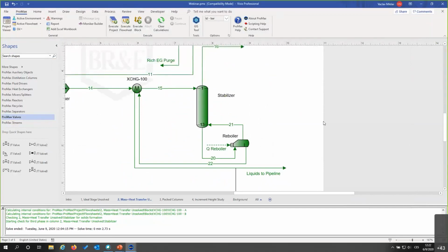What you can always do is reach out to a vendor, and he will probably give you a trustworthy value for HETP, maybe even over some range of F factor or something like that. But what if you want to investigate different feeds? What if you want to investigate multiple packing types? What if you want to change the operating conditions significantly? What if you want to operate at different pressures and temperatures? That's of course going to affect the physical properties as well. So there are a lot of things that can affect HETP, and it's really hard to come up with some value.